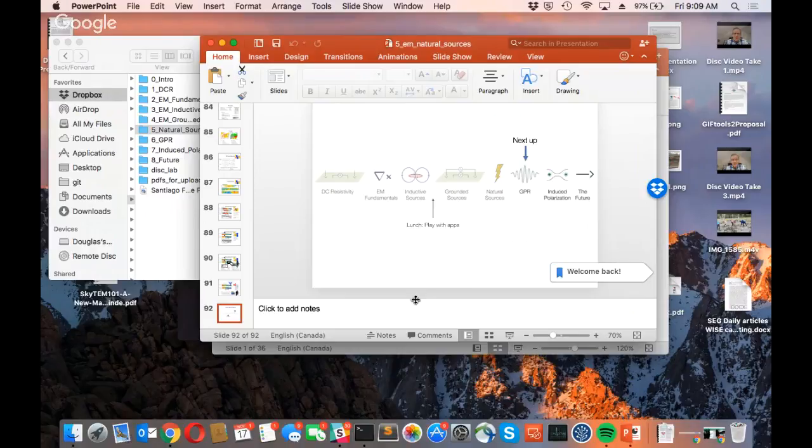Whereas if you present it in terms of the fundamental aspects, which is just, okay, I'm going to put a current in the ground, and that current's going to flow. It's going to generate charges wherever there's a change in the electrical conductivity, and it's those charges that generate those electric fields or voltages. I think you get a much deeper understanding about what is going on.